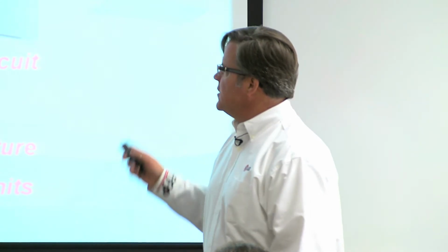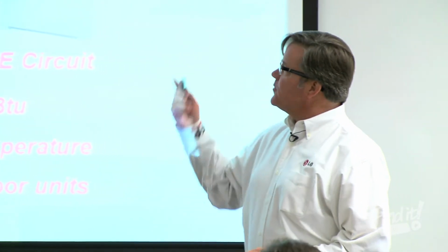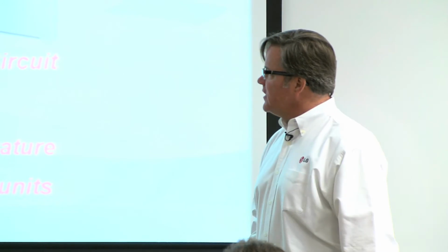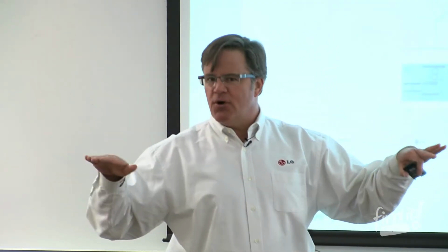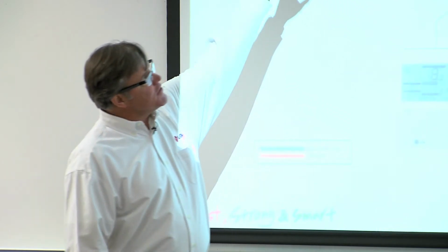So we've got basically, we said we've got a big outdoor heat pump out there. You can connect to, you see here, from 13 to 72 indoor units. They go up to 42 tons, depending on the manufacturer you're dealing with. So you can really get together a big system of these units. But the foundation of this thing, the thing that if you're talking about VRF you have to be able to distinguish between, is heat pump versus heat recovery. And so we're going to give you a skim through overview of what the difference is between heat pump and heat recovery.